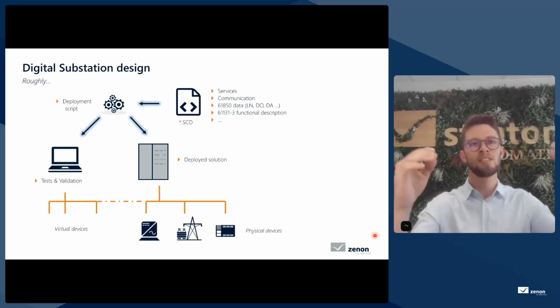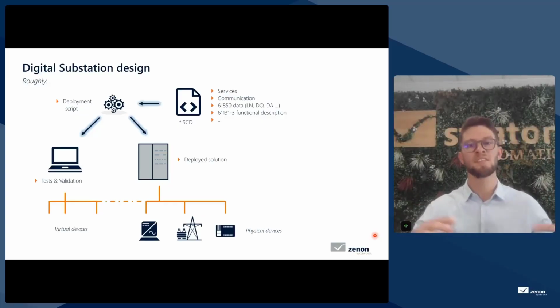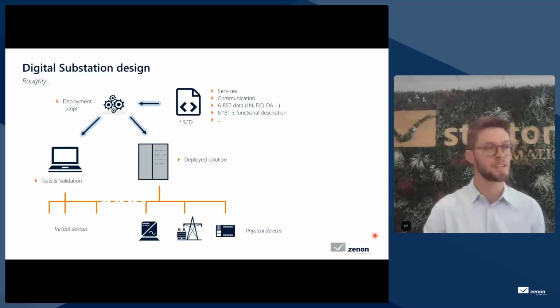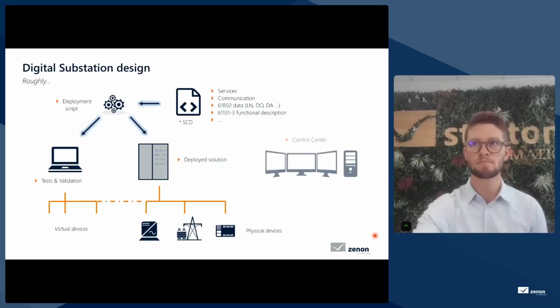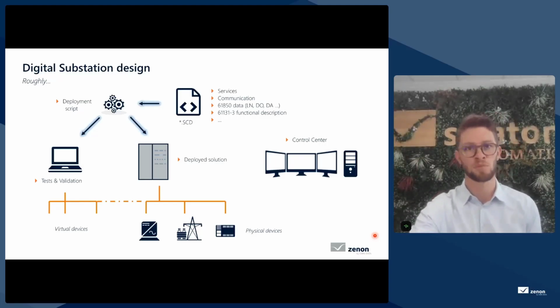And this deployed solution will communicate with all the physical devices. Of course, as everything is standardized via the IEC 61850, the deployed solution can communicate with virtual devices, and the test lab can communicate to physical devices, of course. And above that, you have your control center. So basically, this is roughly the overall design of a substation, I would say.